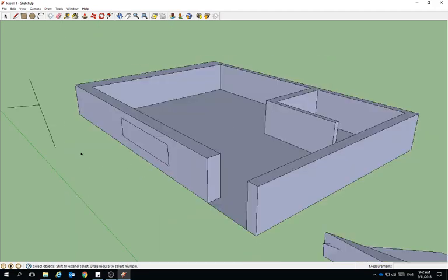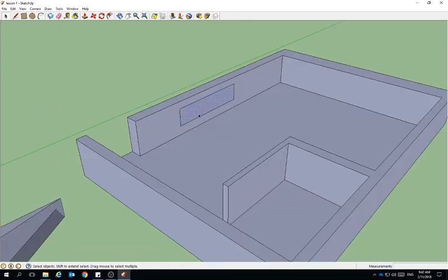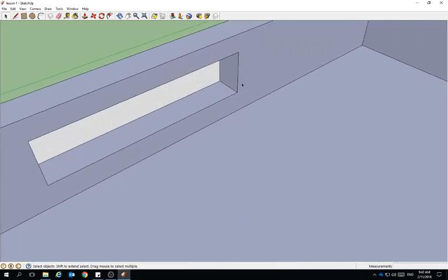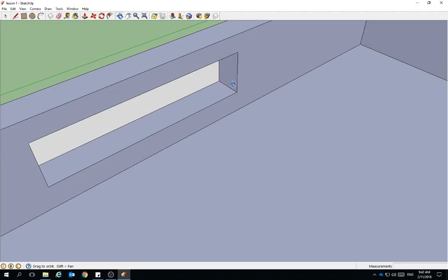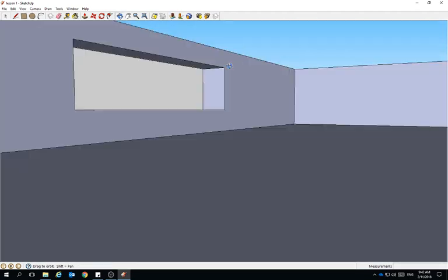So I'm going to get rid of that. I'll get rid of these lines I've done over here, using just a selection box. I can delete the whole lot together. And now I'm going to select this rectangle and delete it. All right, so what that's done now is I've still got the bit of the line left in there, and that allows these to then be solid rectangles, which makes it look like a window frame.